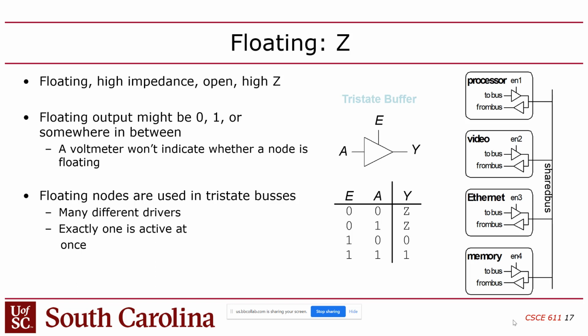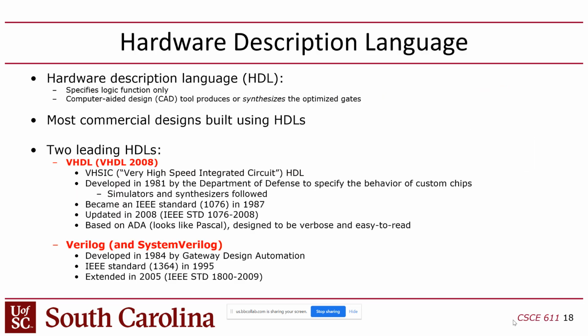One difference, by the way, between SPICE and Verilog: SPICE is a circuit simulator doing an analog simulation, whereas in Verilog you're doing a purely behavioral binary simulation. As a result, Verilog simulation is much faster, but you're not able to put analog modules in there. You can't put a capacitor or a resistor inside your SystemVerilog, because SystemVerilog is only for behavioral logic. So we talked about that. Now let me come back here and give you a little bit more background.